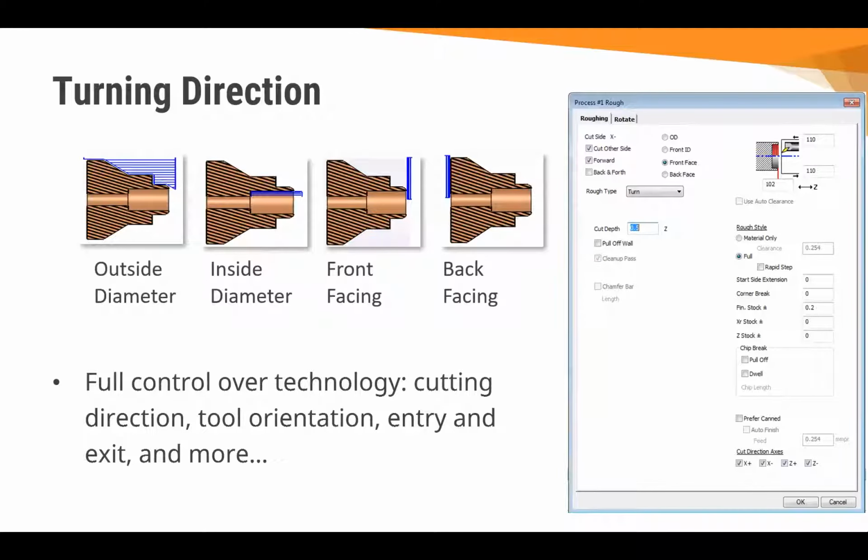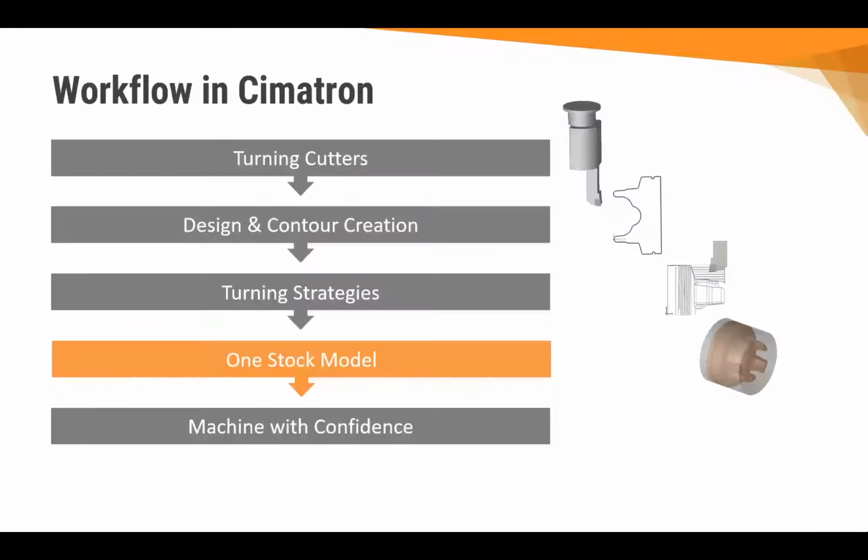We can look at how the roughing or finishing procedures are being created in terms of outside diameter, inside diameter, front face, back face. We have full control over the technology with regards to cutting direction, tool orientation, entry and exit positions.